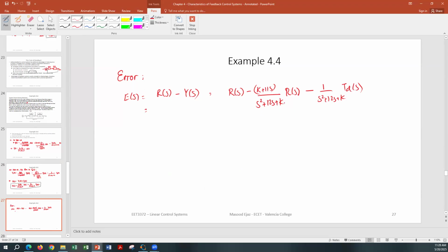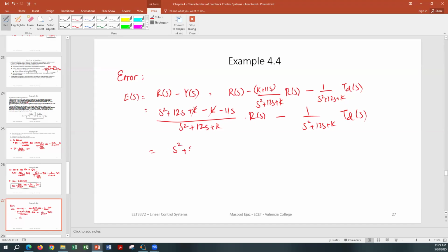So the error signal due to both inputs is going to come out to be s squared plus 12s plus K minus K minus 11s, over s squared plus 12s plus K, times R(s), minus 1 over s squared plus 12s plus K, times TD(s). K cancels out, 12s minus 11s is just s, so s squared plus s over...